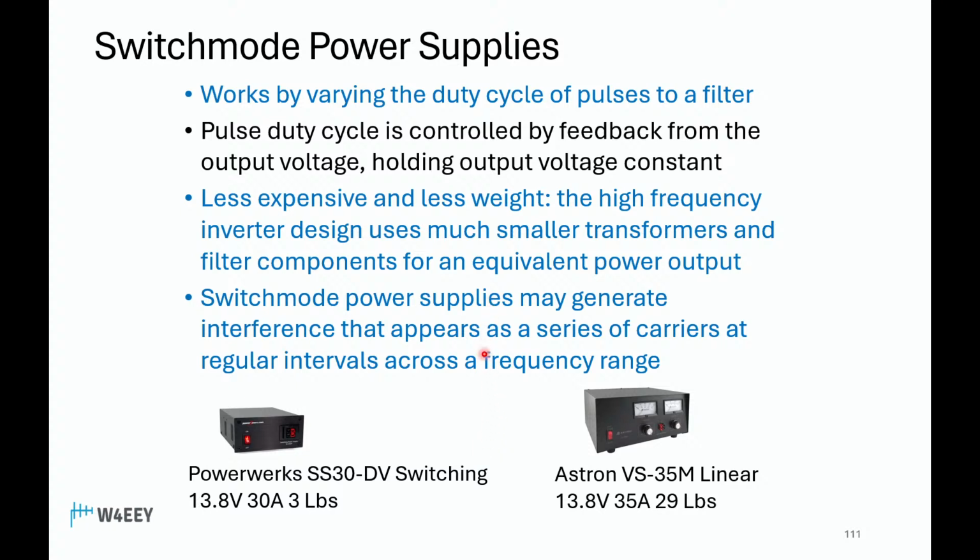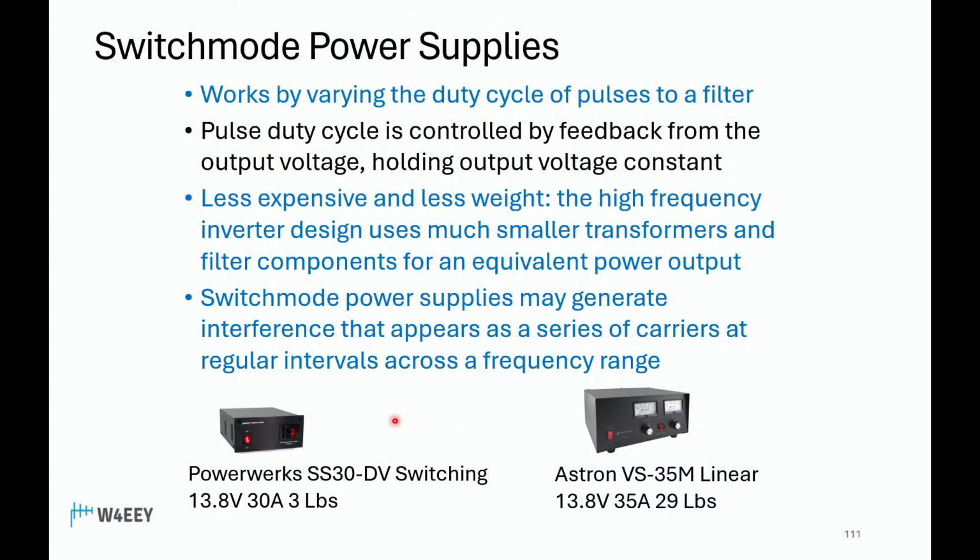And people don't think about, and we're talking about ham radio power supplies here, but the little cubes that you're powering your cell phone with, that's a switch mode power supply. So those little power cubes are really RFI generators. Yeah, the little cubes that run your cell phones and all kinds of other electronics, they can be horrible. They can really be horrible. All kinds of stories we could share there. So these are things you need to know.